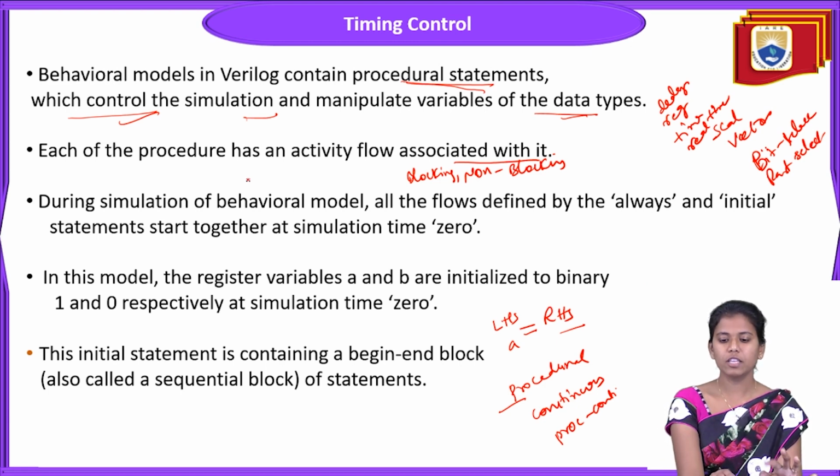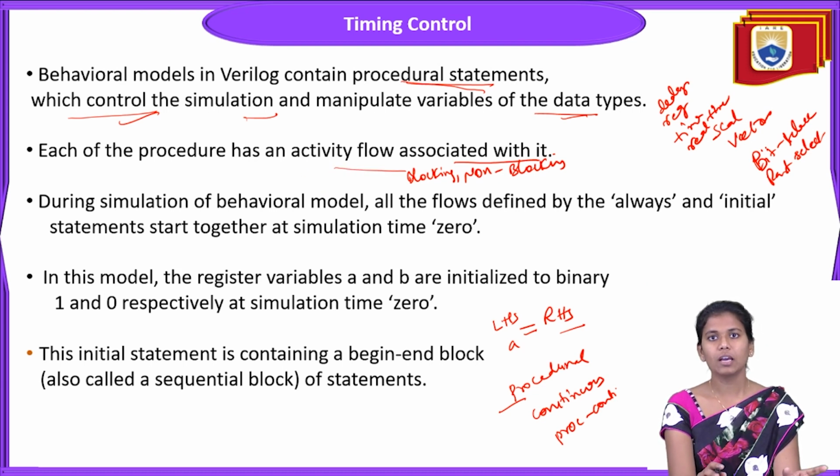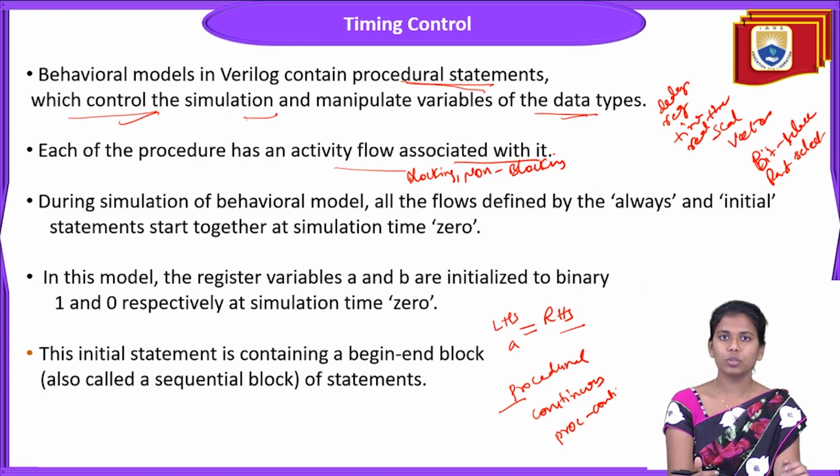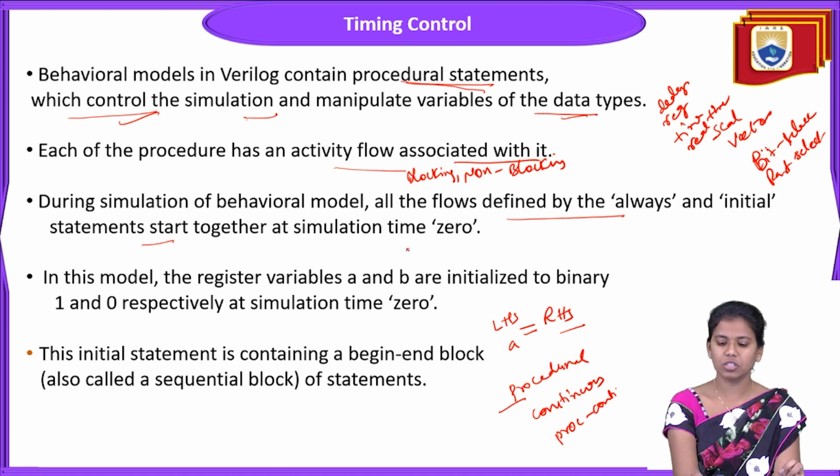Here also, with the procedural assignments or whatever continuous assignments you are considering, there is an activity flow associated with them. With respect to the assignments you are considering, there is a flow, an activity flow associated with that particular assignment. Also, during simulation of the behavioral modeling, all the flows defined by the always and initial statements start at simulation time 0.